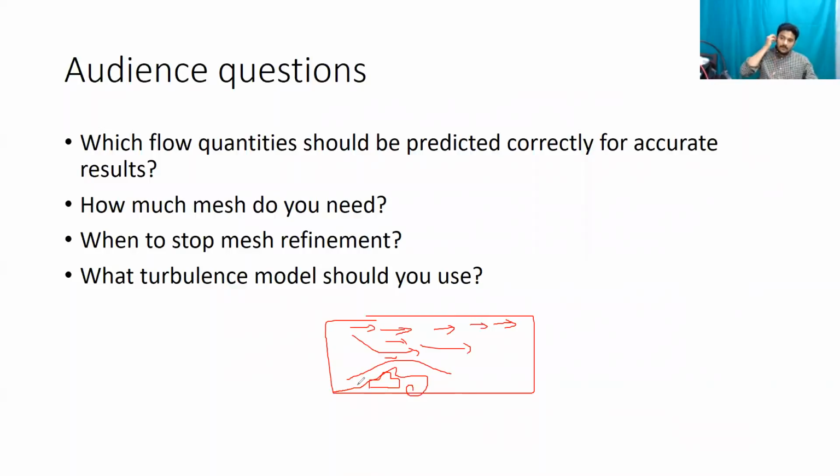So when you're talking about the boundary layer, well, turns out inside the boundary layer, it can be split into two regions, and you can do it. You can prove this from a theoretical framework. You can do some experiments and also determine it. There is a layer called as the viscous sublayer, and then there is an outer layer. In the viscous sublayer, your flow often tends to be laminar, and outside, your flow tends to start becoming turbulent.